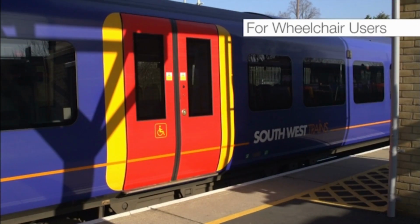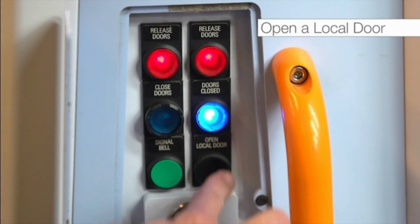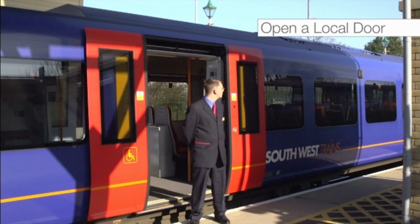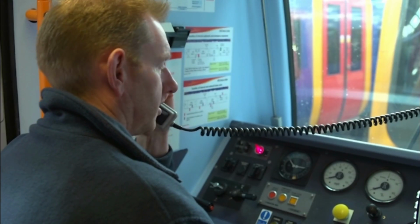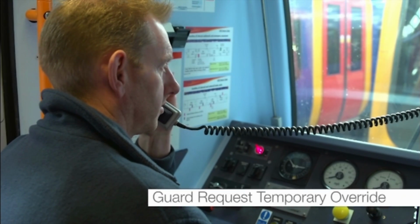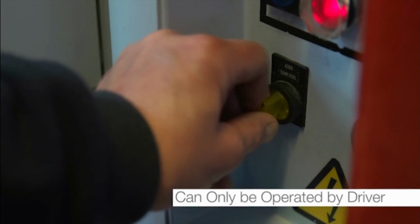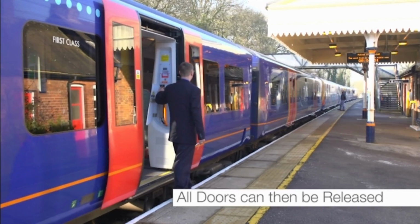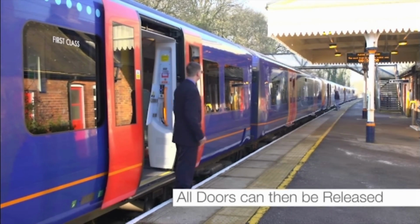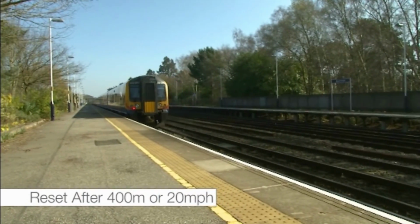To allow wheelchair users to join or alight, it is possible to open a local door, providing that it is on the platform. On multiple units on platforms able to accommodate the whole train, the guard must contact the driver to request a temporary override of the ASDO system. The temporary override switch can only be operated by the driver. Once operated, all doors can be released. The system will only reset itself once the train has moved 400 metres or achieved 20 miles per hour.